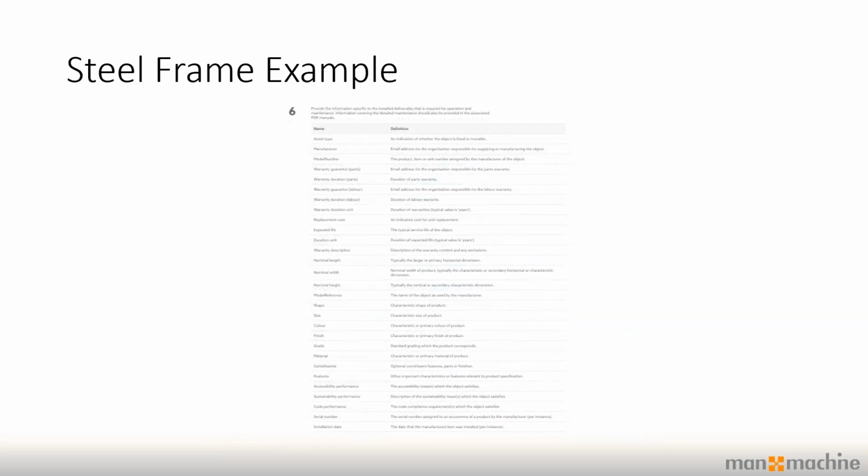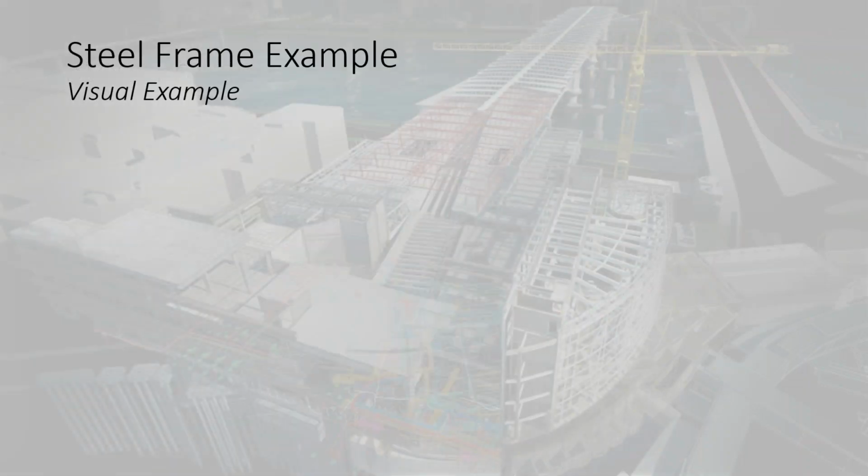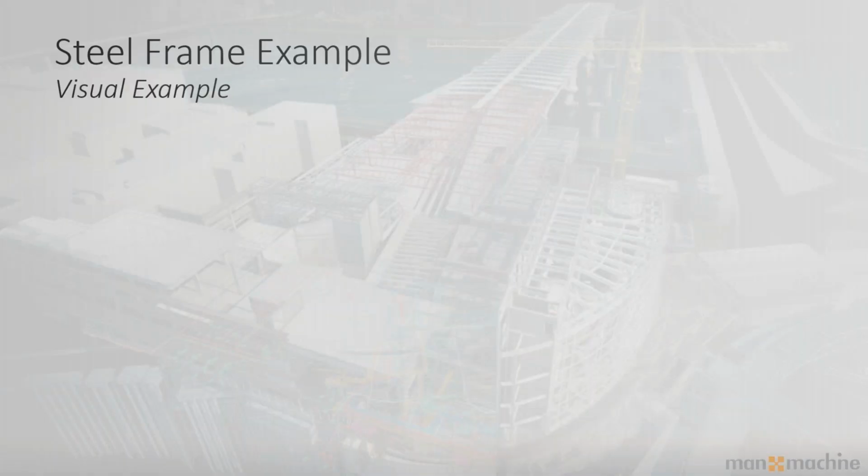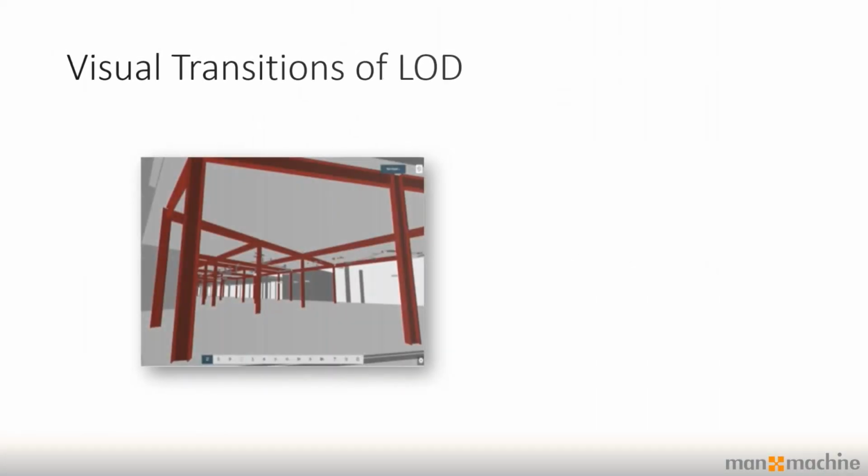There is no LOD6, there is just lots more information to add. So the biggest detail model level we can get is LOD5, but at LOD6, we can get a load of additional properties, which is basically COBie, to define what that product is. So only additional information.